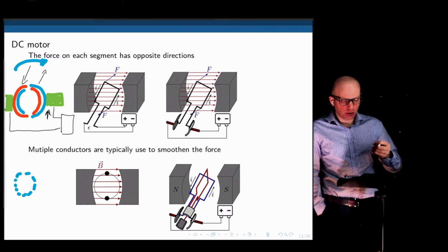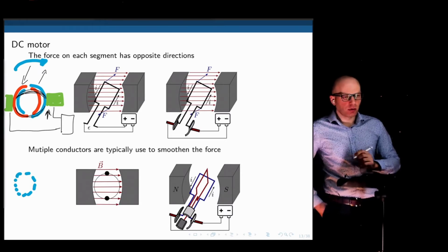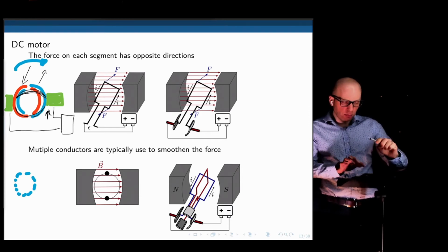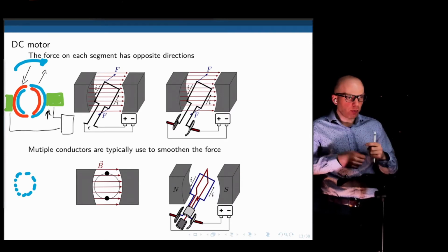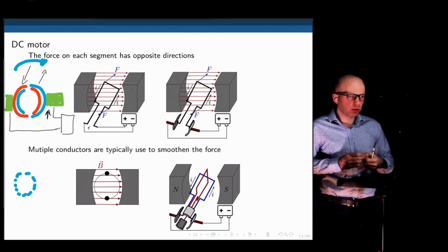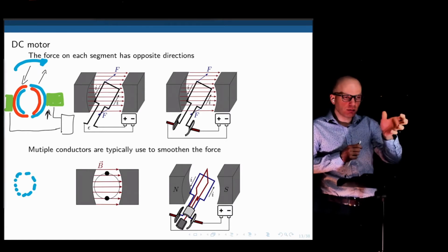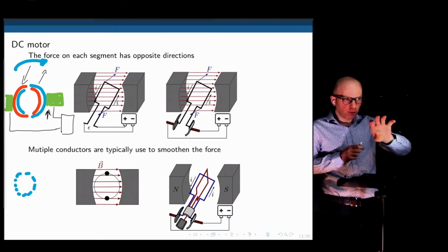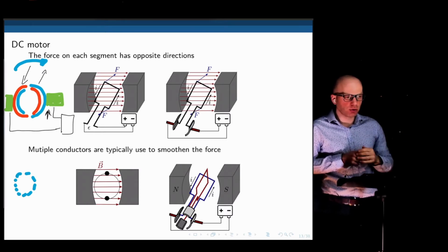When you switch direction, exactly, let's say at this point here, when the commutators rotate like that, and passing that point, now you see that the red one will touch the right, the blue one will touch the left. We arrange that in a way that this will occur when we pass the point of 0 EMF. Think about these two wires, this blue and the red, rotating. For this rotation here, if you do another 90-degree rotation, the blue is still connected to the right one. Past 90 degrees, now the red one touches the right one. That's how the commutation occurs. Okay, yeah, I get it. Thank you.